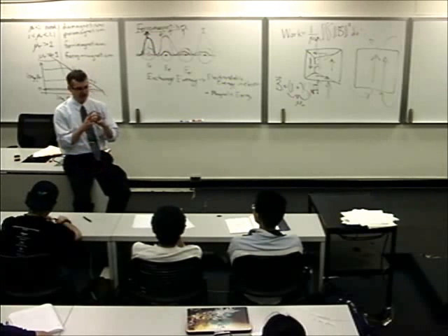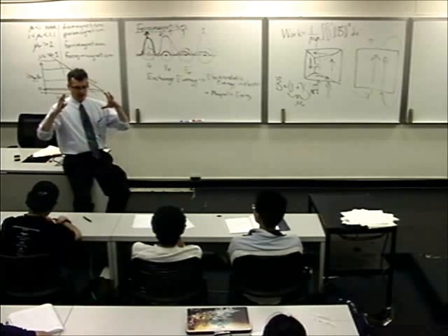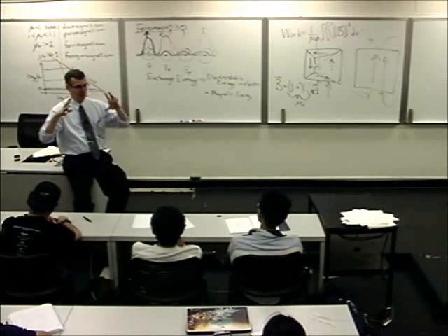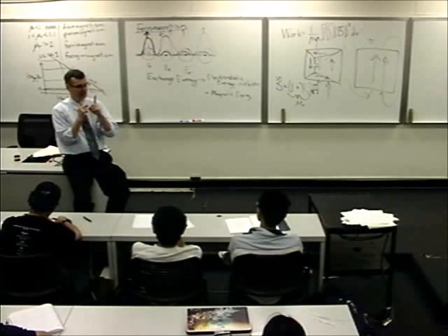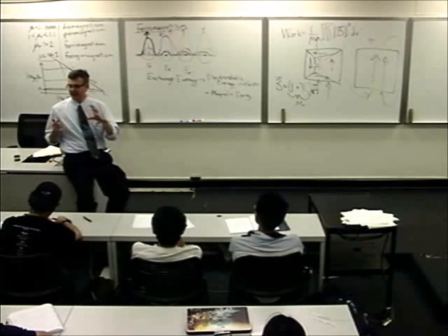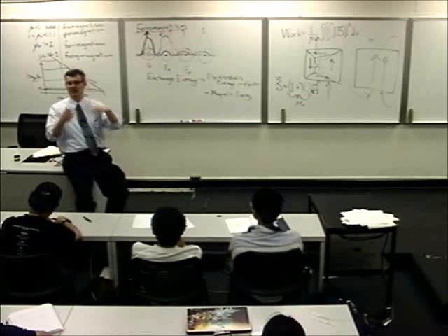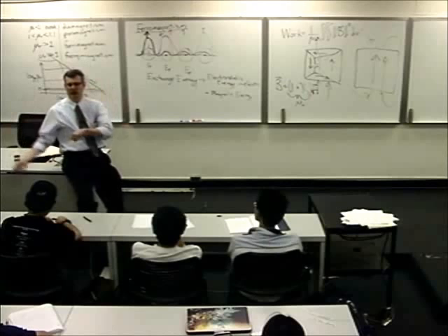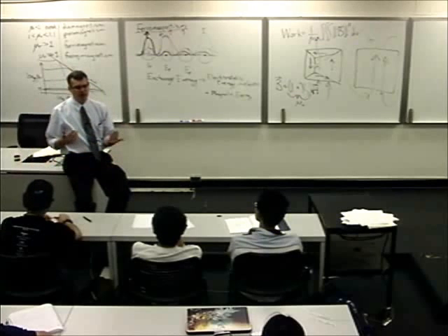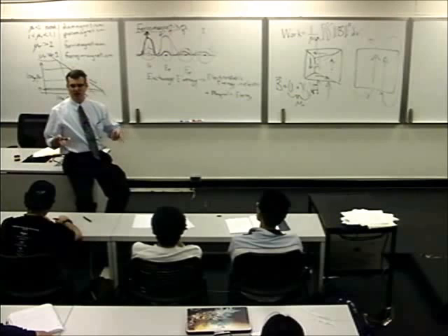So what's happening there is that the particle is in this kind of peculiar quantum cooperation state where all the atoms inside the little particle are cooperating with their magnetic moments, but you can change them really easily because there's not enough of them there to make the critical mass that you have to reverse the polarization and then swing it back. So it has the frequency cutoff of a paramagnet, but it has the mu sub r of kind of like a crummy ferromagnet.